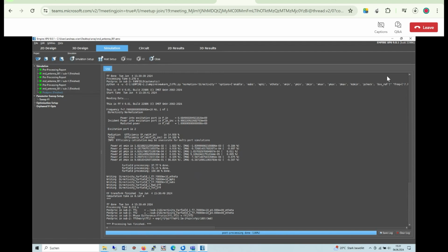Now you see in the last rows, the post-processing says my file copy, two ones, FF1, FF2. Then I have the first equation. The phase difference is the ratio of these ones, FF1 over FF2, and the theory curve is this formula we have seen in the radar theory for the phase difference. Now let's go to the 2D result tabs,